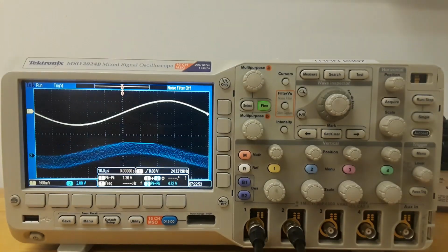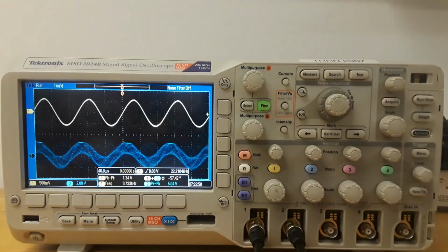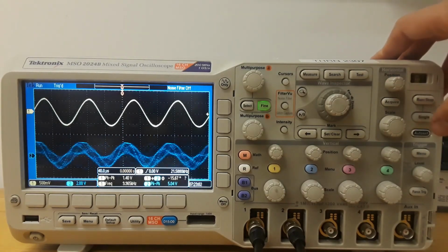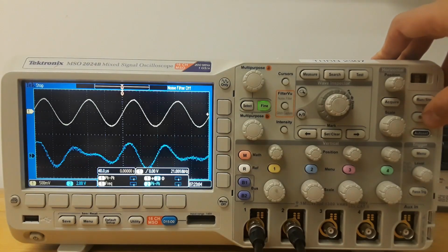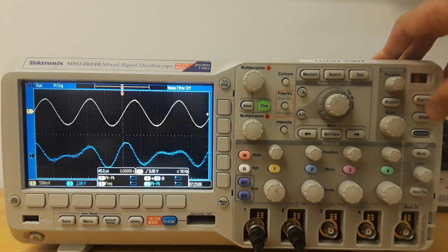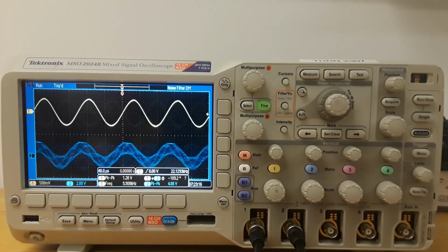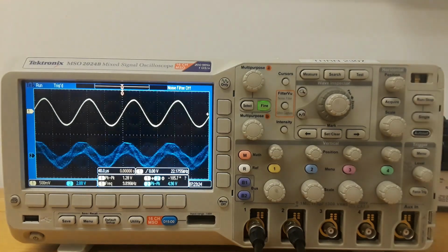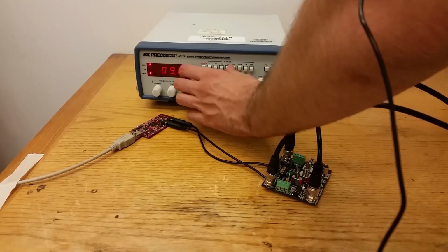That's close enough. Well, we can definitely see that we have something resembling our input there, though it's definitely really noisy. Let's take a look at that signal again, and we'll screenshot that. We're not seeing too much helpful there. We've got our input signal, we've got our output signal kind of matching that, but there's a lot of higher frequency noise going on in the meantime. And let's drop it down to 5 kilohertz just to see what happens.